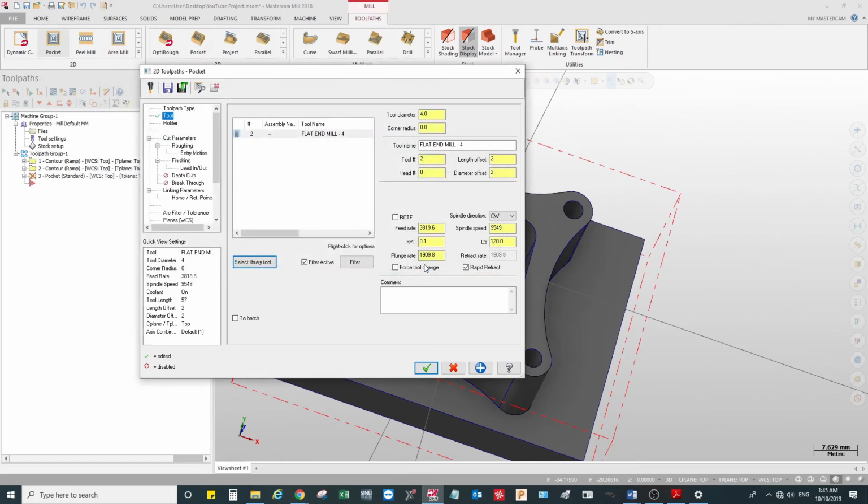You see that the diameter is about 6 millimeter, with a radius of 3 millimeters. So a 6 millimeter end mill would do the work, or you can go with a 4 end mill and still get the result. I think I'll go with the 4 end mill and machine this pocket.